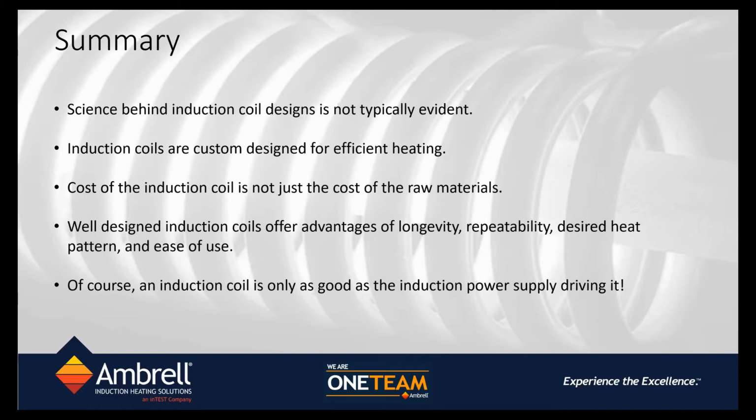It doesn't matter what that part is, whether it's magnetic or non-magnetic, the interaction is similar. It is more pronounced in magnetic parts, not as pronounced in non-magnetic parts. So that's why it doesn't matter what the material makeup is, all metals tend to levitate right near the induction heating fields. And given a strong enough magnetic field, the metals will actually float in air.